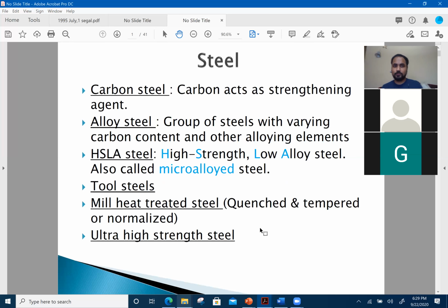Also a question I had: my general understanding is that on a TTT diagram, the stuff further out to the right would be closer to equilibrium, right? So then I would expect that if bainite is so far to the right, why is it not on the phase diagram? What takes up that space? Bainite is also a metastable phase. It approaches equilibrium, but it is considered metastable because if you just let bainite sit for a long time, it transforms into pearlite again.